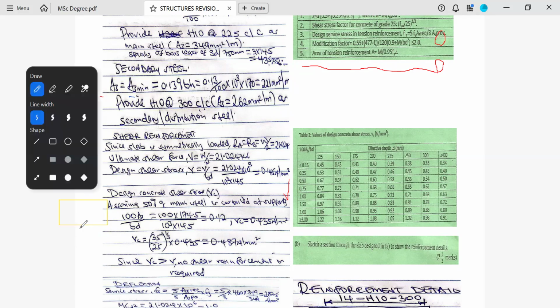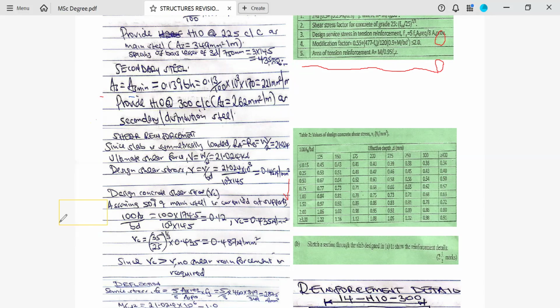If I have my bar here, it will come from here, but it will stop at this point. Now we call them alternate bars reversed. My bar coming from my second bar will come from the end of this, but not reach the end of that. My next will come. So this is what we call curtailment.